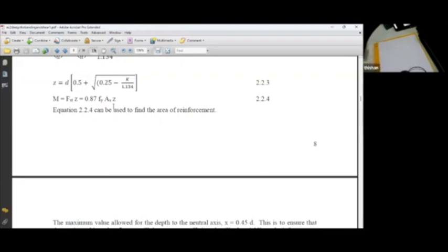Now, when you are designing a building, there are 2 levels at which you can do the design. The first is the preliminary design, where you get the general arrangement drawing properly done, when you are selecting the structural form to be used, where you look at the alternative slab systems, right? Come up with the most economical slab system. So that is the preliminary part of the design. If you get the preliminary part of the design correct, only then can we do an economical design. Otherwise, you can still do a design.